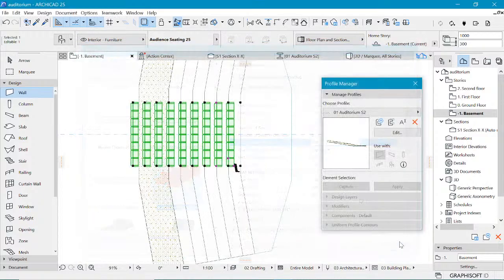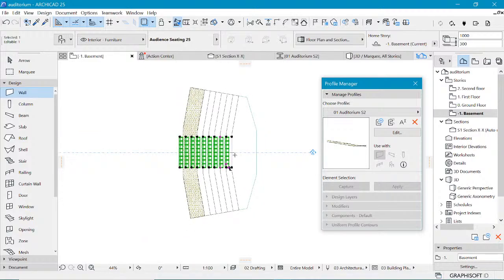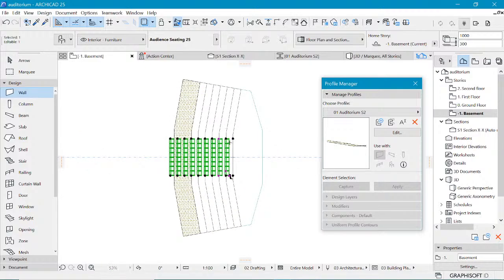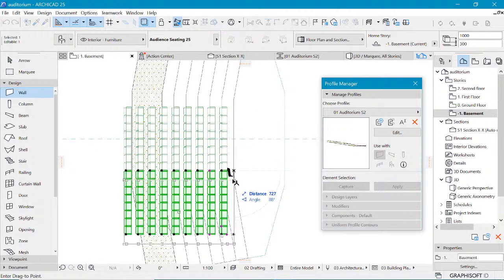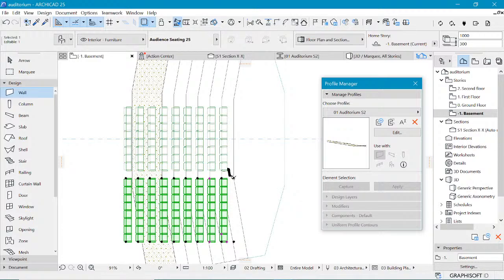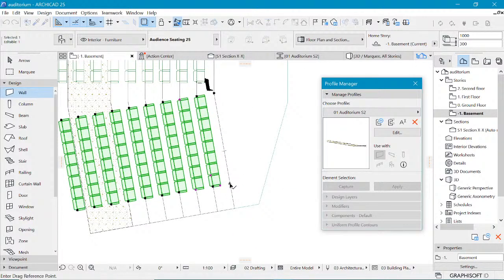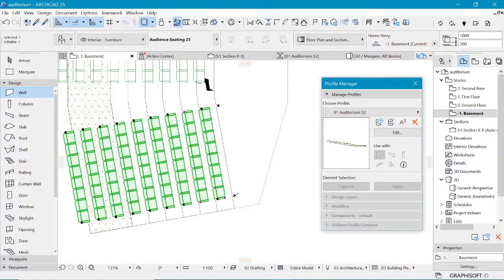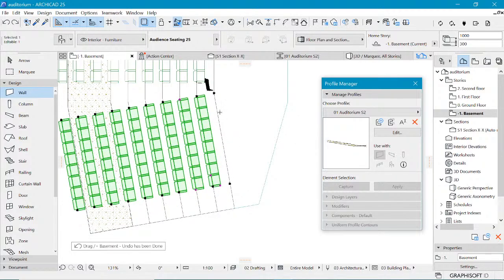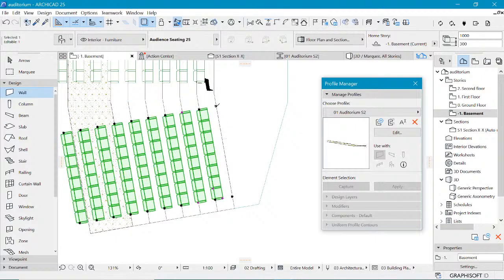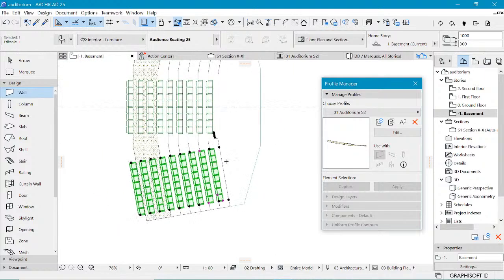So let's say okay, and now we are going to put this thing here. So let me make a copy. Remember, Ctrl Shift D is what you need to make a copy. Ctrl E to rotate, and now we have ourselves something here. And this is about 1.4, so 700 should work to centrally place this, although we have not followed this. Yes, something like 700 in that line should be able to work, so that's much more acceptable.